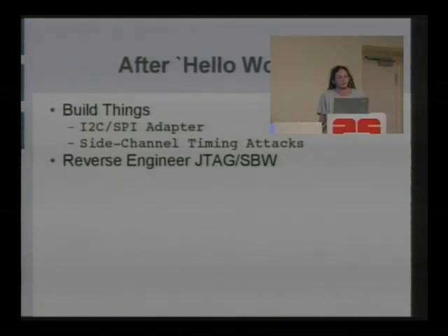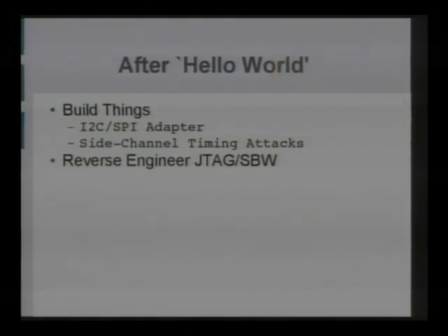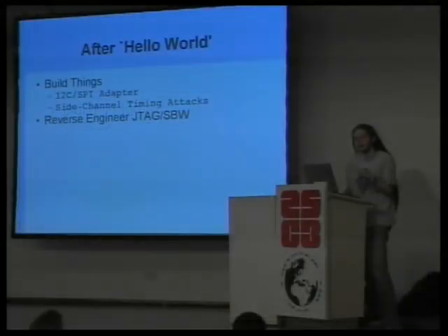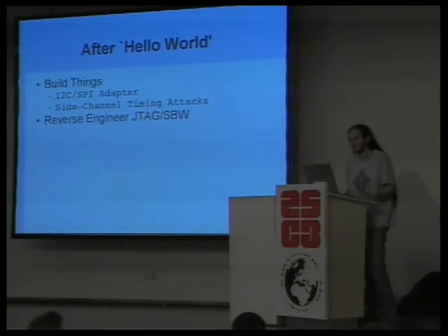If you look at the Bus Pirate, it's from Hackaday. It's a PIC microcontroller and a serial adapter. And then the PIC microcontroller does bit banging on any protocol that you specify over some GPIO pins. Well, this could do the same thing because it exposes its GPIO pins. It also exposes line-level serial if you need to do fast communications with, say, a Zigbee radio.